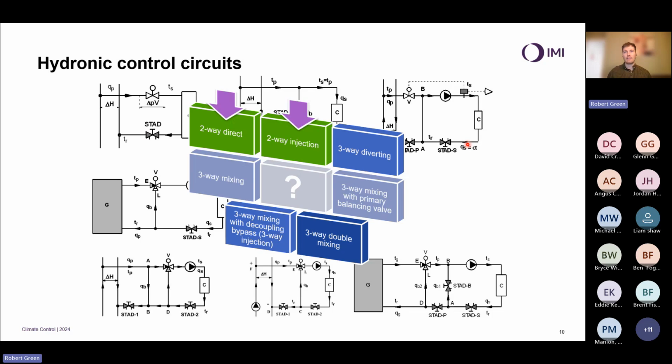And this is something that's very typical around things like air handling units, where we need a higher level of control than something like a fan coil. And I'll talk about why we introduce the injection circuit. Very prevalent in Europe. Being a proud English guy, something they don't really do in the UK. When I go over to Europe, they say, well, they don't. But there are some real good reasons for it, and we can really get improvements in control there.